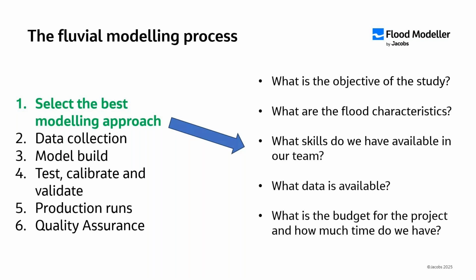And also, what is the budget for the project and how much time do we have? You can spend as long as you want fine tuning hydraulic models to get the best representation of real world conditions as you can. But in reality, you might not have the time or the budget to build that. So sometimes you need to build the best you can with the data that you've got. Also, really complicated flood models take a lot of time to put together. So that's another thing you might want to consider.